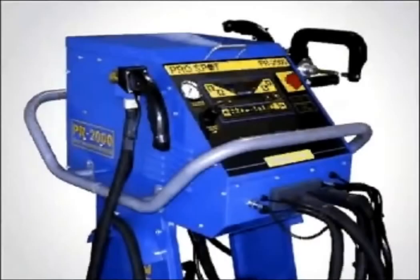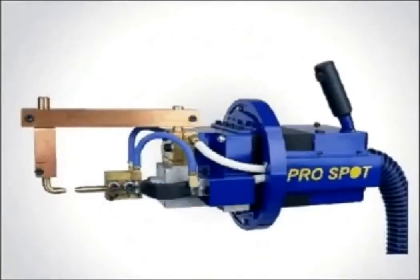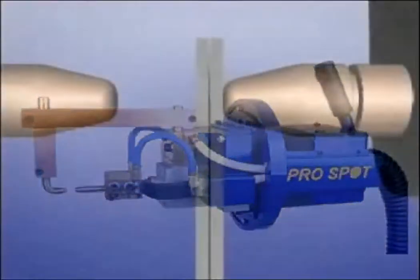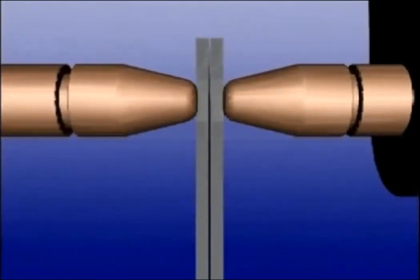A resistance spot welder is designed to deliver a low voltage, high current electrical pulse. The weld electrodes are made of copper because copper has a low resistance to current flow, which allows it to conduct electricity with ease. Steel is a very poor conductor of electricity, and it will resist the weld current as it flows from the spot welder.